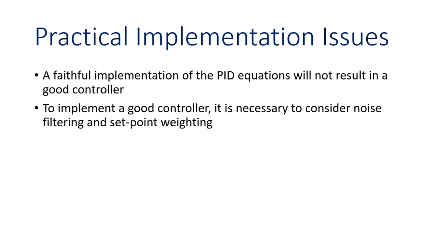And for set point weighting, when you do the integration or derivative, what happens if you have a constant set point? In that case, you have a zero derivative term, so the derivative term is not working. To avoid this problem, we introduce set point weighting.